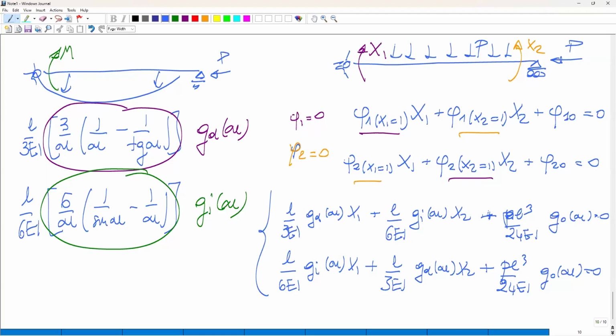The buckling failure is, as we said, a situation in which the structure completely loses its stiffness against the sway movement. If I have a zero stiffness, you can have infinite displacement, but not only a displacement which goes to infinite. It means that any value of the displacement is possible because stiffness is zero. You do not control it anymore. So you do not have only one solution. You have infinite of them.